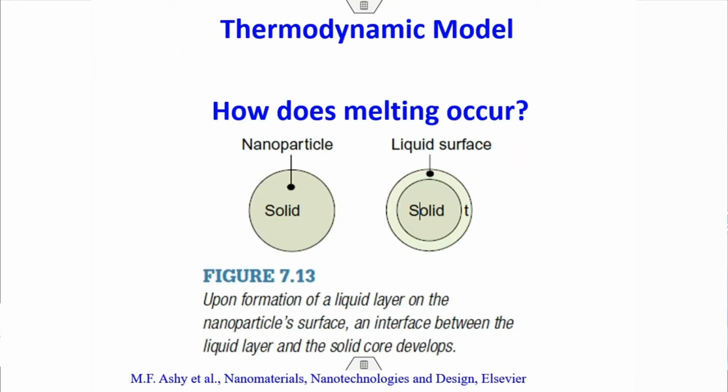Well, the most important thing for this discussion is how the melting starts. Normally, for a free nanoparticle, melting will always start at the surface. That's very clear. At the surface, melting will start. So the liquid which nucleates at the surface will slowly grow and move inside the solid spherical nanoparticle. You can use any kind of shape, but for the sake of simplicity and to make things clear, we used spherical nanoparticles and showed how the liquid front, which forms at the surface of the nanoparticle, can move inside and melt it completely. And this is how the melting normally happens in nanomaterials.